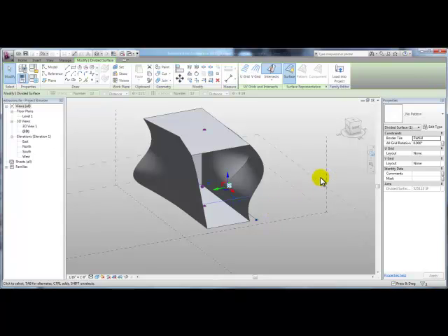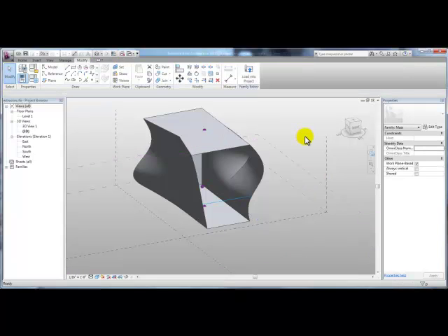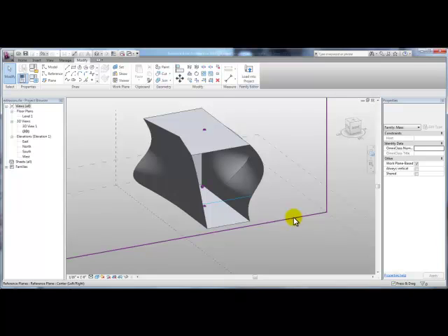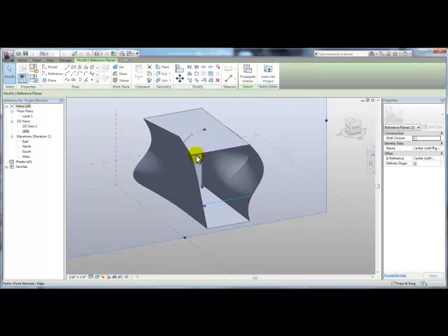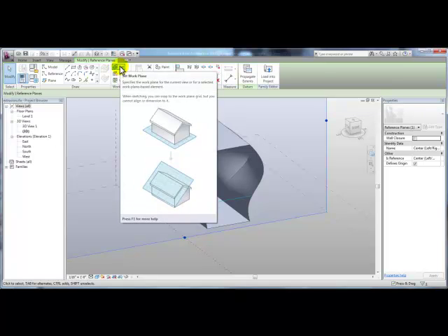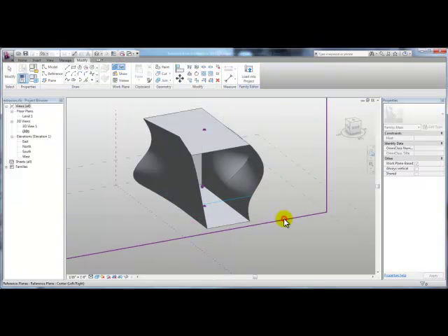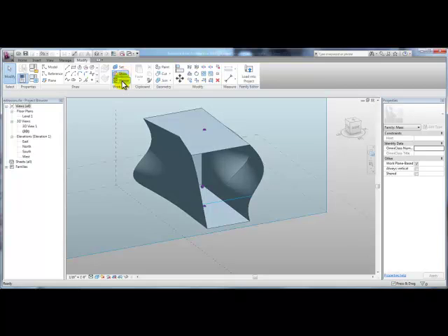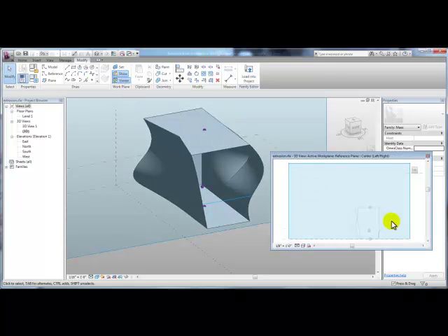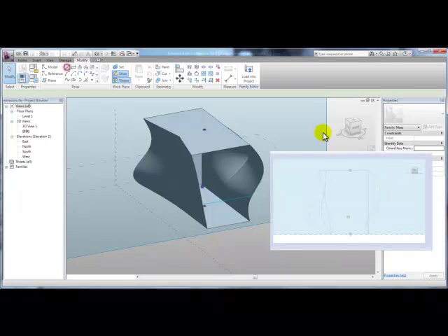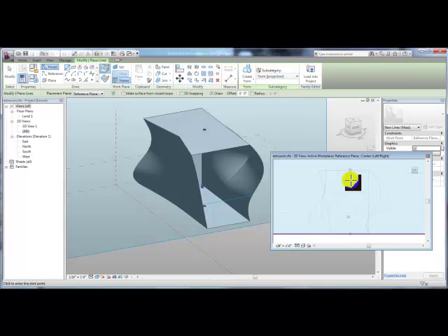It's based on a new pattern that you're creating with this level. Another way to create your own pattern using intersects is to select a reference plane like this one here. We'll select this vertical reference plane and set that one. Picking the Set tool, we can set this reference plane and show it, and then use the viewer to actively see that reference plane in relation to our model and draw lines that will represent our new pattern.